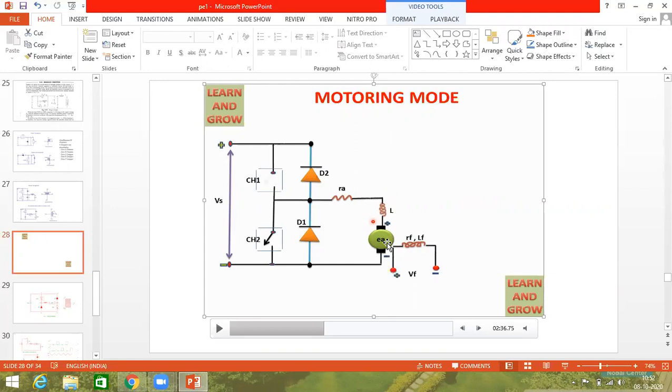Understood all of you? The explanation we are discussing is far beyond the textbook explanation. So the first circuit will be tough, but you will be in a situation where you can compare with even university students. You will be in advanced mode explanation. Okay, right. So case 2 is all about generating mode or regenerative mode, where when the electric train has to be stopped, the back EMF of the machine is greater than the supply voltage. Therefore, the motor will act as a generator and energy is transferred from the generator to the source.